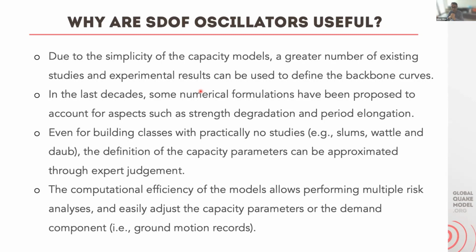For some of the building classes, there are no studies, of course. If you think about slums in some parts of the world, or specific building classes like wattle and daub, it's not like we have shaking table tests or even pseudodynamic tests or a lot of numerical analysis for those buildings. But through expert opinion, or even by comparing with other building classes, it is perhaps slightly easier to come up with some capacity parameters for these, let's say, informal or non-engineered building classes.